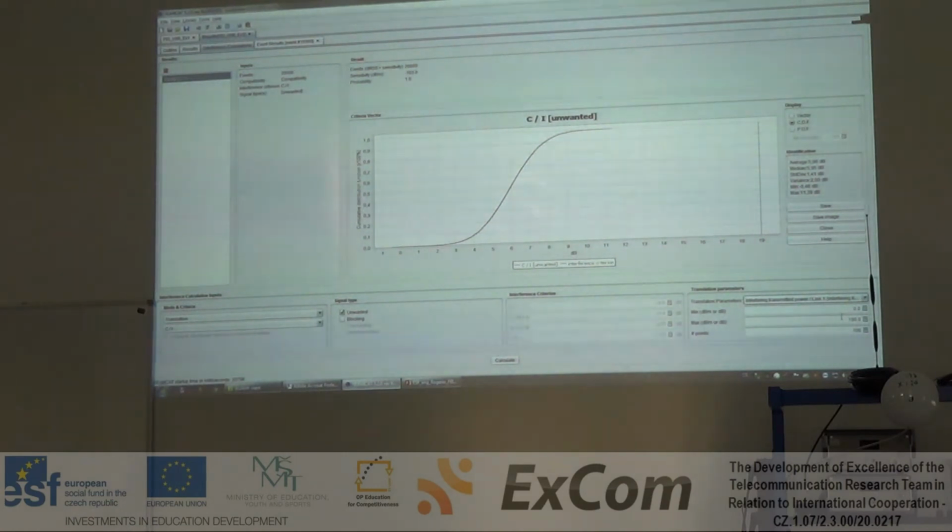Someone remembers what was the value that we used on the simulation? It was 30. So with 30 dBm, I'm already at 100% of interference. So I really don't need to go up to 100. It's not useful. So you can decrease this 100 to 30. That's more than enough because I know that at least at 30 dBm I already have full interference. So I don't need to go up. The number of points for the simulation is 100. That's okay. And then you can click on calculate.